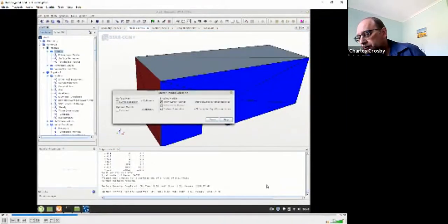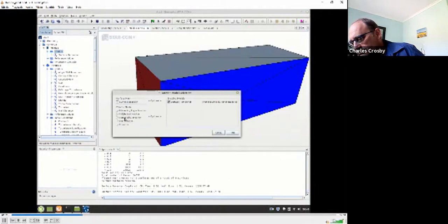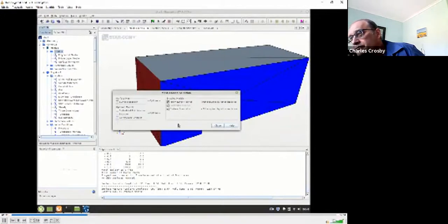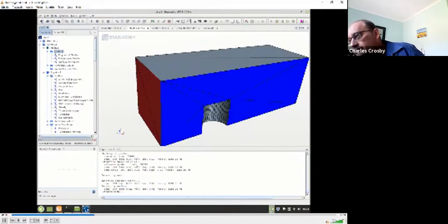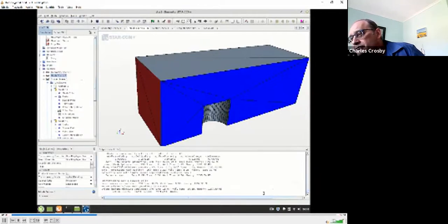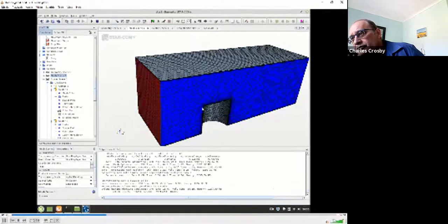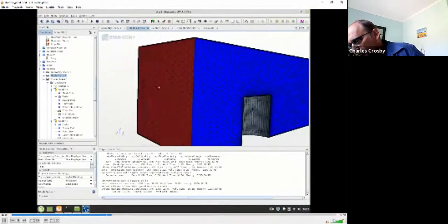We also have the option of using polyhedral meshing. So let's back away again, drop the tetrahedral meshing and select polyhedral meshing. Once again with a prism layer mesher. We've already remeshed the surface, so let's generate the volume mesh. It's finished the polyhedral mesh generation, and as you can see we're back down to a cell count of around 132,000 cells. Let's apply the volume representation, and now it looks very different. So this is our polyhedral mesh.